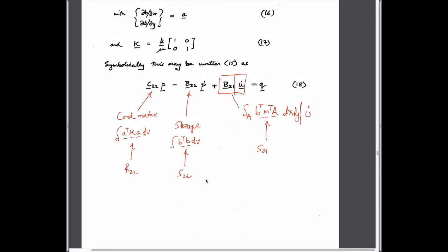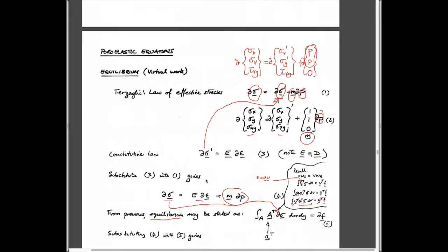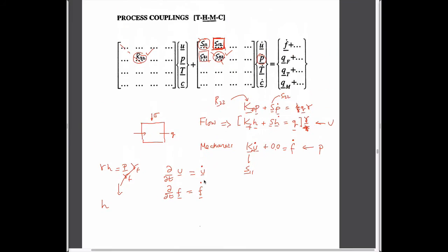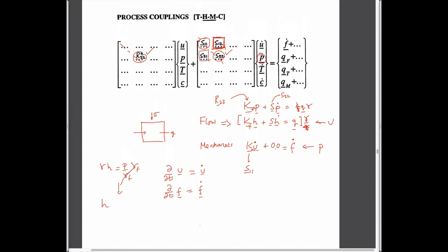And so those are the expressions. So what we've done, it's probably not all that interesting to delve really deeply into this, but what we've done is we started off with the circle terms. Conductance and fluid pressure storage, written only in terms of pressures, defined only in terms of pressures. We started with a second system that overlaps it, which defines a stiffness related to the forces through displacement. Instead of forces, we use displacement rates and force rates, and defined only in terms of displacements, and therefore not coupled to the fluid system through pressures at all.